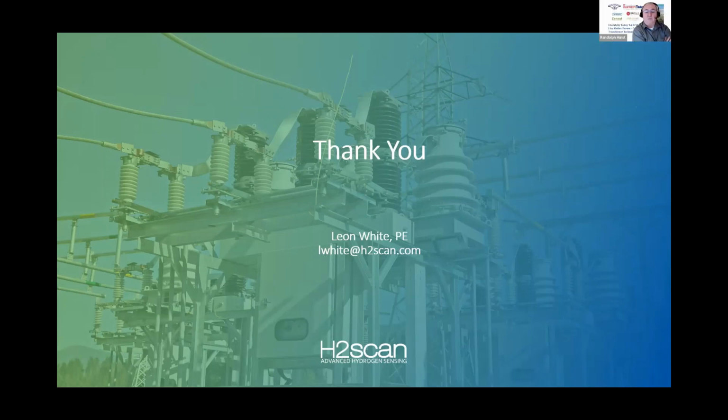Okay. Can single gas monitors be used on all size transformers, even to supplement multi-gas monitors on large transformers? Absolutely. It's interesting that the hydrogen monitors are getting smaller and smaller today, to the point where they can pretty much monitor any fluid-filled transformer. Whether it's a 1,000 MVA large transmission transformer, or even an oil-filled PT or CT, there are monitoring solutions available for those today.